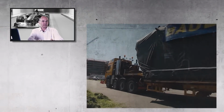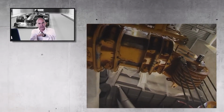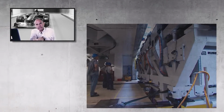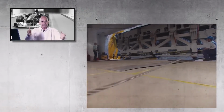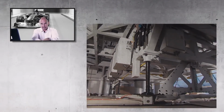Now, an air bearing is nothing particularly hard to understand. You supply high pressure air through a microporous material, and this microporous material allows the air to come through. It's still at quite high pressure, so the harder you push down with your steel belt, the more that is resisted by the air pressure coming through the porous bed material. The only problem with that is this porous bed material with lots of air coming through is pushing air underneath your moving belt, and unless you evacuate it, you then have an air bubble that's going to allow the belt to float, and it'll be sucked up.